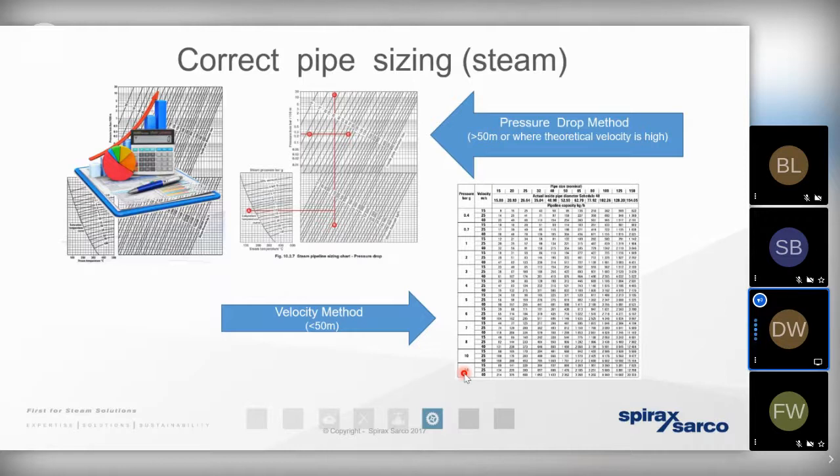If we knew for a fact that we had very poor condition steam, likely to have a lot of moisture and a lot of particulate in it, we'd want to be conveying that at a much more gentle velocity, 15 meters per second. The average would be somewhere between 25 and 30 meters per second. If we were distributing the steam at too fast a velocity, then that's when we're at risk that the moisture and the particulate would create a lot of erosion of those sensitive areas.